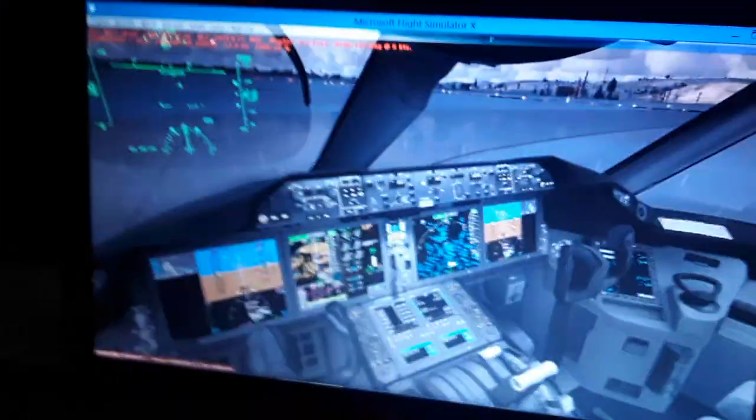When we start the engine, we have the engine start process. We're going to start a small auxiliary power unit, the APU of the aircraft, which is going to provide us with alternate current. I'm going to show you right now how I start the switch and make the engine start demonstration later. We're going to shut down the engines and restart them. In the process of restart, we need the pressurizer from the APU to pressurize the engine starter. Also we need alternate current, direct current also.